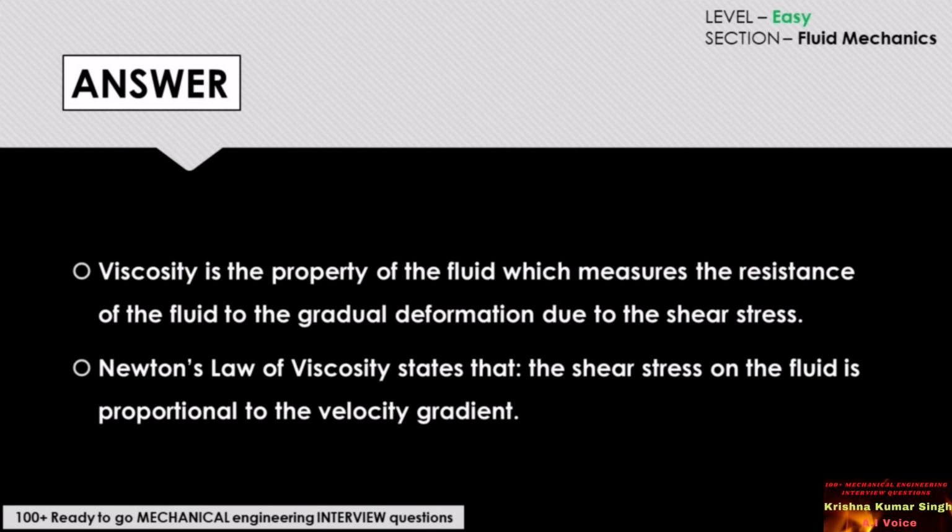The answer to this question would be: viscosity is the property of the fluid which measures the resistance of the fluid to the gradual deformation due to the shear stress. And Newton's law of viscosity states that the shear stress on the fluid is proportional to the velocity gradient.